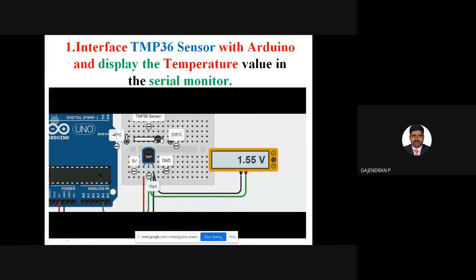If I know these two ranges, this is only possible if you have a simulation tool like this, then only is it possible to do the mapping immediately. Or else, step by step you need to feed the value and scale your values. So I will show you the simplest method. If you have this kind of simulation tool, we can observe the entire range of the temperature as well as the analog output voltage. If you map the analog output voltage exactly, immediately we will get the Celsius output. Likewise, we are going to change the temperature range and observe the output.